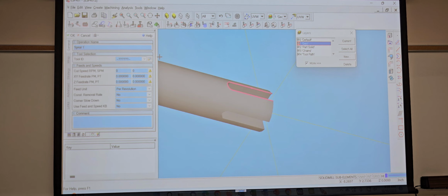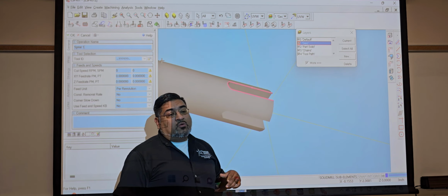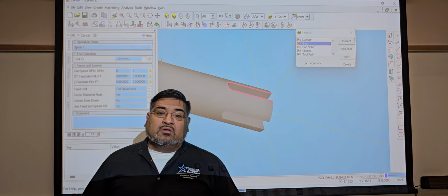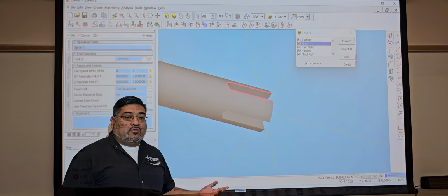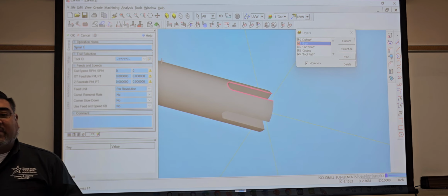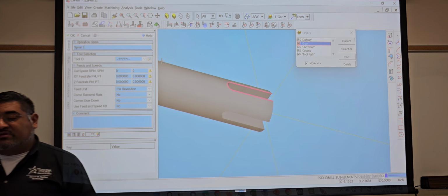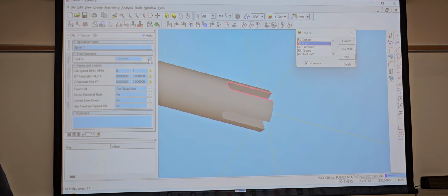Select your tool. With this one, our radius is 0.375, right? So we can't get a tool that's greater than that. Now, since we're using contouring, it's just gonna make one line in and one line out, right? So we don't wanna use something very small that the step over isn't big enough to take it out. Does that make sense? You can use a 0.375, 0.4, 0.425, which should work, right? But let's just use the 0.375. Most likely it's gonna be our best bet.